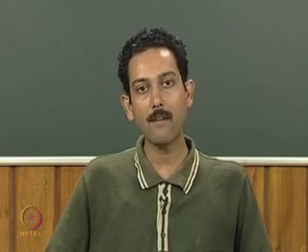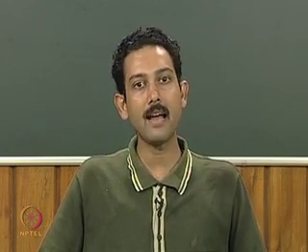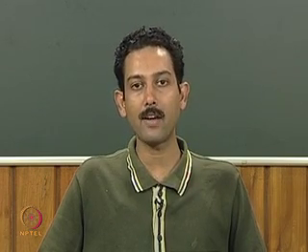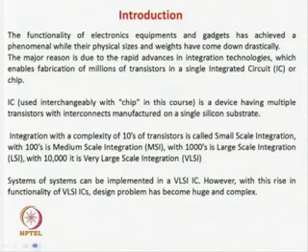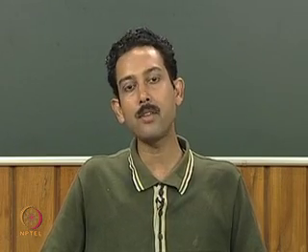We have also learned in basic digital design, which is a second year undergraduate course, how the same thing can be done in hardware. You can connect some D flip flops, then go for finite state machine minimization, where the present state is 0 and the next state is 1, then again the present state is 1 and the next state is 0, and so forth. You use a Karnaugh map or the Quine-McCluskey method to minimize the circuit, and then we implement the circuit, which is the hardware, and it works very similarly to software like the C program.